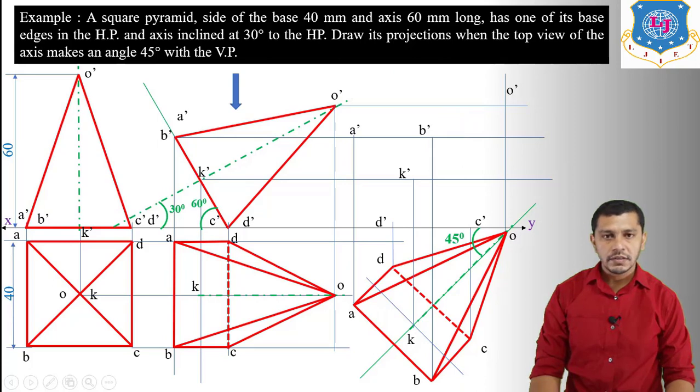And third point is that we will apply after drawing the visible outlines in the front view, that 2 hidden lines will never intersect and 2 visible lines will never intersect. That means any of the edges which are intersecting the visible outlines in the front view are going to be hidden.